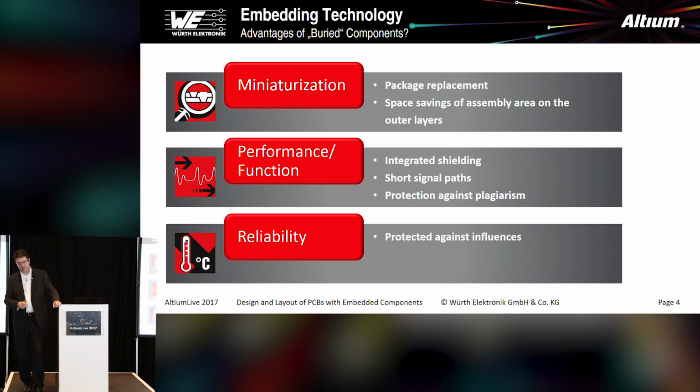And in previous works, when we look at those gear shift box sensors, those have been standard double-layer PCBs. There were some Hall sensor ICs on it, some caps, some resistors, nothing critical, nothing complex. But they were sealing those components with transfer mold. And the PCB and the transfer mold just have different CTEs. So this is working against each other. There will be a crack for sure. And this crack is wandering to the inside. And as soon as this crack reaches either a component or a track, the oil will dissolve the copper, and the sensor, or whatever it is, will be gone.